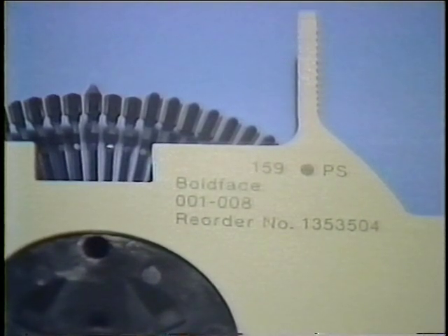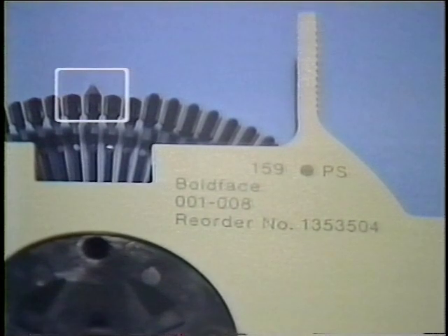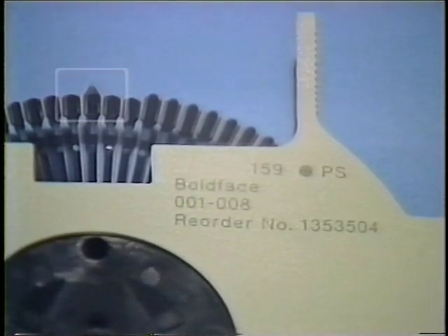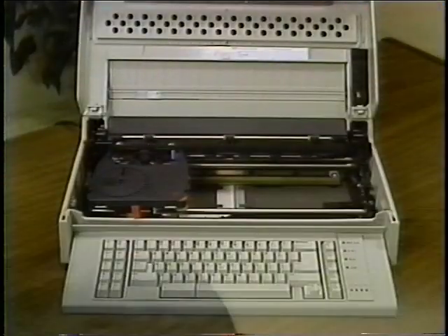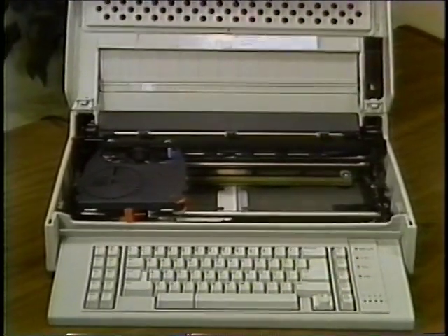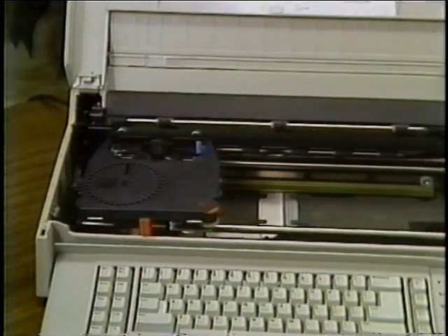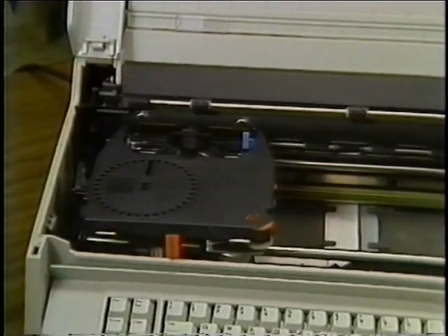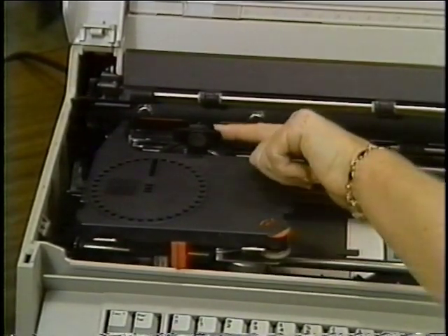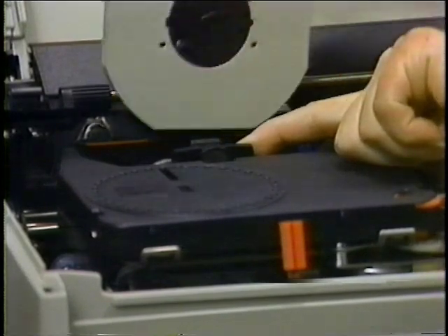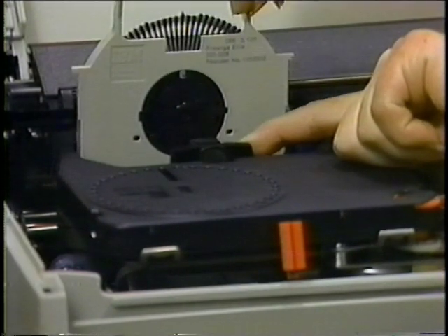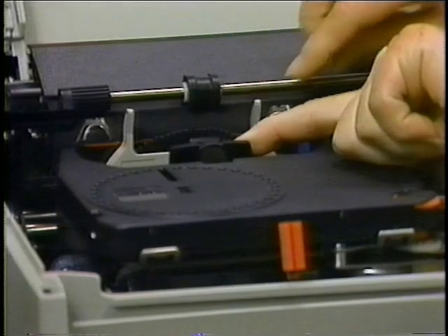When the print wheel is in its home position, the wheel is detented in its case so that the character petal with the pointed top is straight up. To install a print wheel in the machine, pull the print hammer back, and place the print wheel in the machine with the IBM logo facing you. When the print wheel is in place, allow the print hammer to return to its normal position.